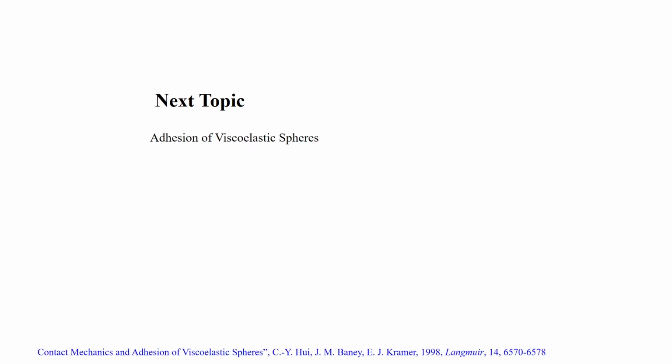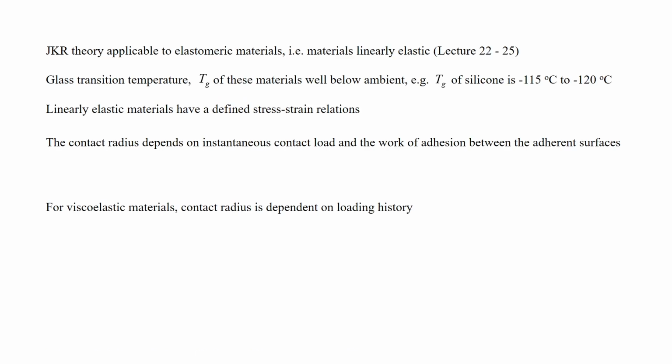So, now I will go to discuss the adhesion of viscoelastic spheres. Viscoelastic brings a different dimension to the problem, and it is about time. The JKR theory we derived earlier for adhesive contact between elastic spheres, we considered in the limit of a linearly elastic material. There was a definite relation between stress and strain, the Hookean law, and we used that.